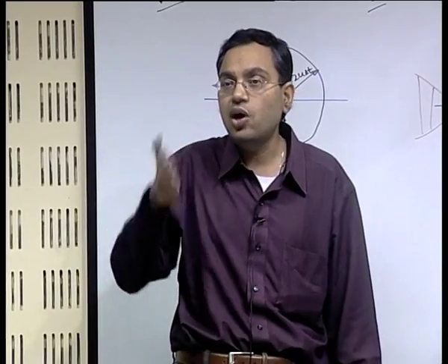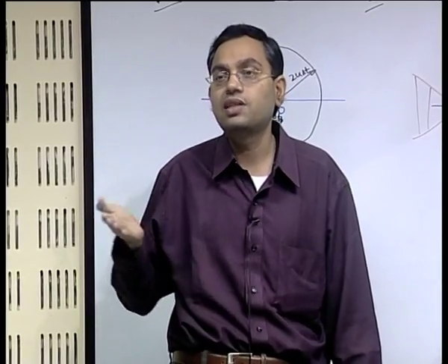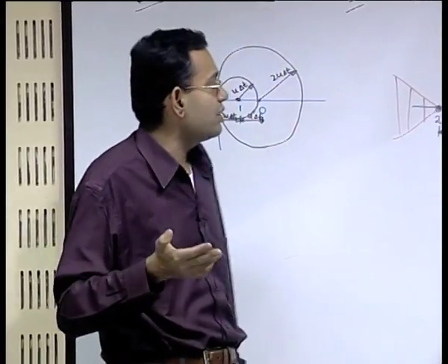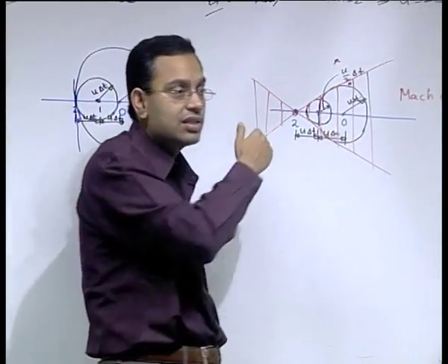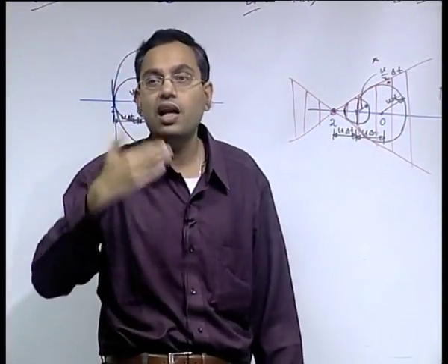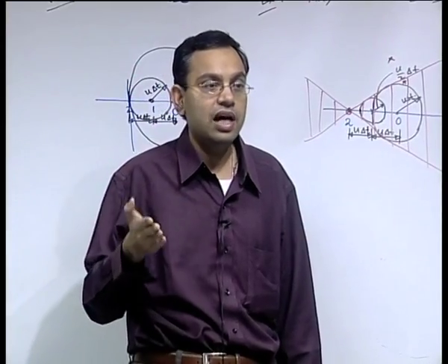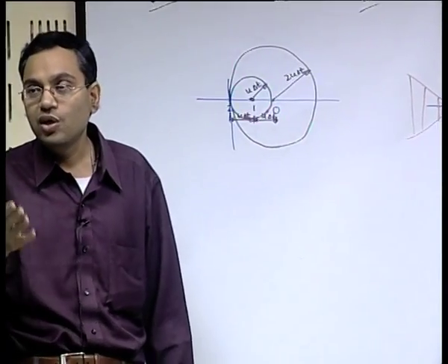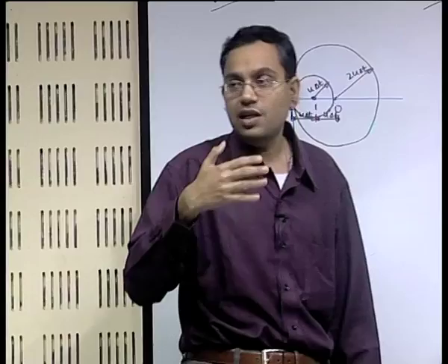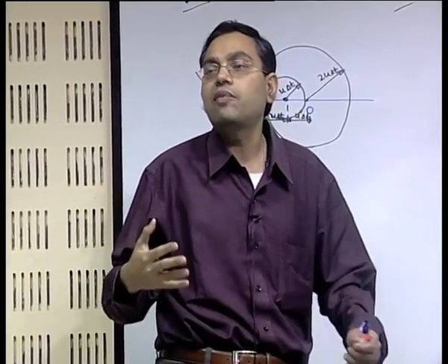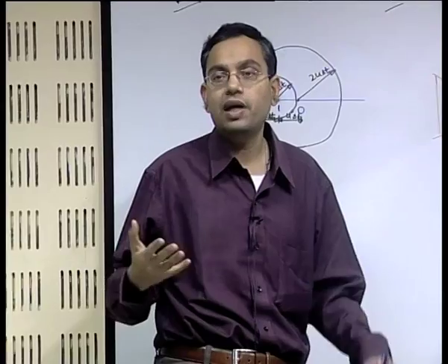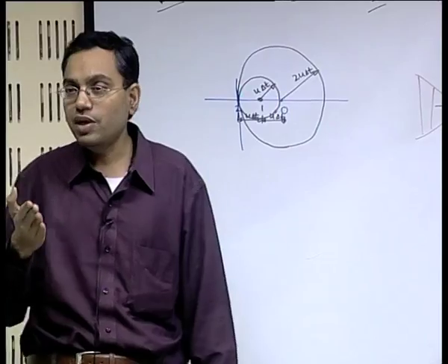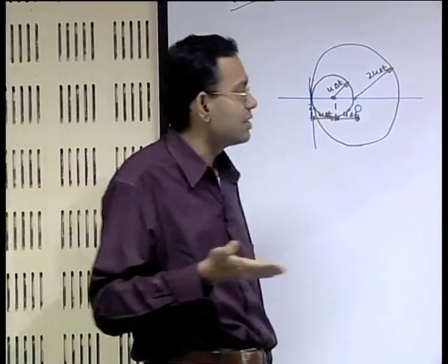So you can have strong discontinuities of properties, that is, you can have jumps in properties of the flow. Those do not take place across these characteristic lines, but across other lines which are called shock fronts, and the corresponding waves of propagation are called shock waves. So since you have this accumulation of disturbances, somehow they have to be relieved, and shock waves are mechanisms by which these disturbances are relieved. So you can have possible discontinuities.